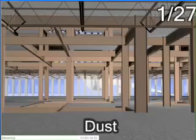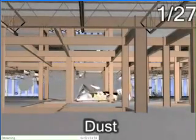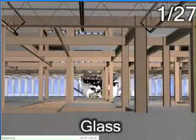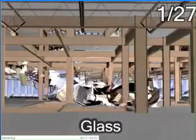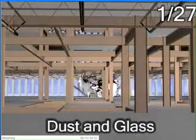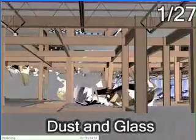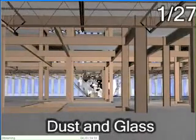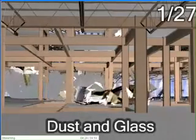Elements that undergo excessive stress are eliminated from the computation by the FEA simulation code. These eroding elements correspond to entities that disintegrate, such as a slab of concrete turning into dust. Although they do not have much relevance from the simulation standpoint, eroded elements are important for the visualization. Eroded elements are used in the animation system to automatically create and control visual effects such as dust and glass shards.